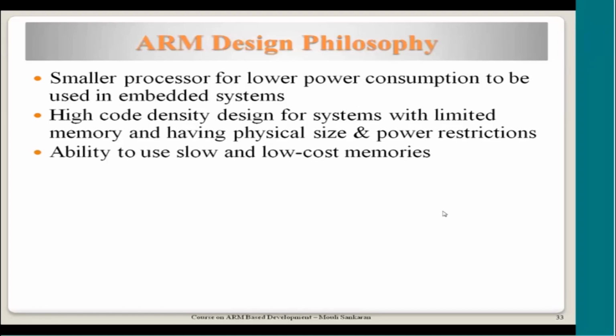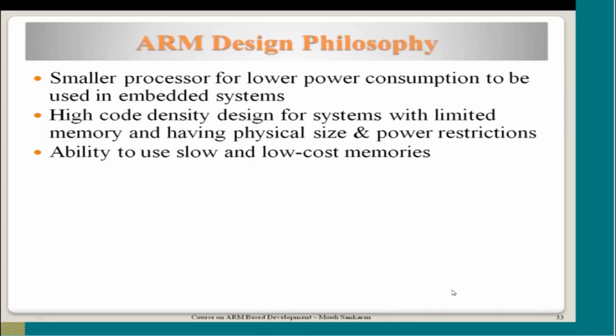And this also allows different kinds of memory to be interfaced, because in the way memories are interfaced with ARM, there is a lot of flexibility and programmability supported, which helps in configuring or building a system using low cost, slow memories as well.